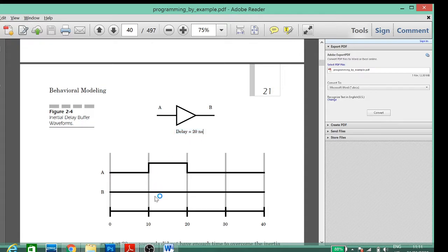Now we will see the graph, how the time periods flow. For 10 nanoseconds, A remains in the zero state. But after 10 nanoseconds, it transitions from 0 to 1. And then for another 10 nanoseconds, it remains in state 1. That means throughout the 20 nanoseconds, the A value is not stable. It's changing from 0 to 1, and after 20, it changes again from 1 to 0.